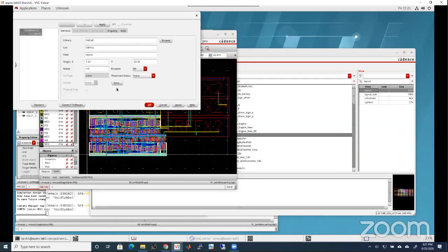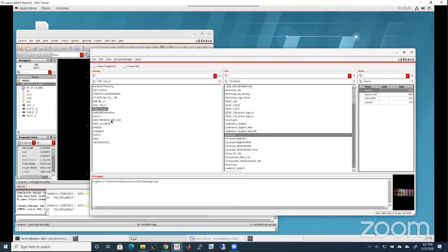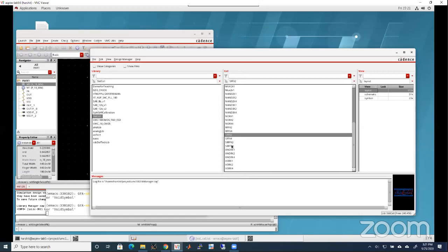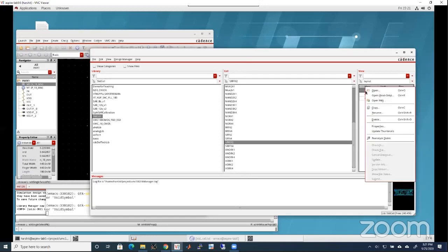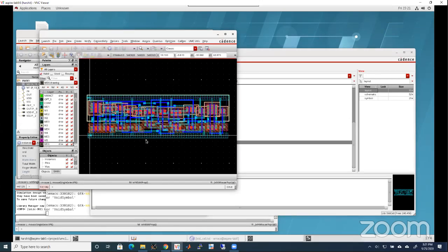Okay, so yeah, this is the actual one. We did not do the D flip flop. We did the SR flip flop, set reset, because that's what we used. So this is the set reset D flip flop layout. You can see that the height is the same always. Only thing that happens is that the thing changes in the X direction. So you decide on the height and you do the connections.